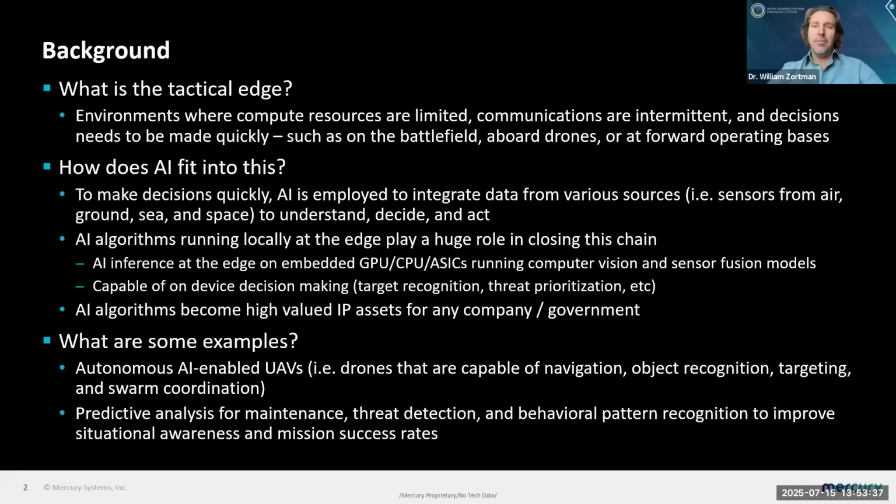Yeah, I mean, you might take a hit if you have to decrypt all your software before you can run it, it takes time. Might take layout space too, depending on how you implement that. We've actually seen people use formal methods in the design process, and when they're using formal methods to verify their software, they actually end up finding fewer bugs later on, and they actually end up getting a quicker design time through security.